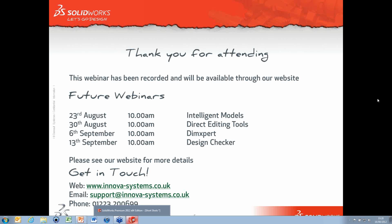Okay, any other questions? Okay, just bear with me here. I just need to scroll up a little bit. So somebody's asked whether or not MatWeb data can be added to the materials library. Within SolidWorks Professional, it doesn't have the ability to add custom materials to the database, but in SolidWorks Premium we do have the ability to add custom materials. So if you can get the material data from MatWeb, then what we could do is actually add that into the system.